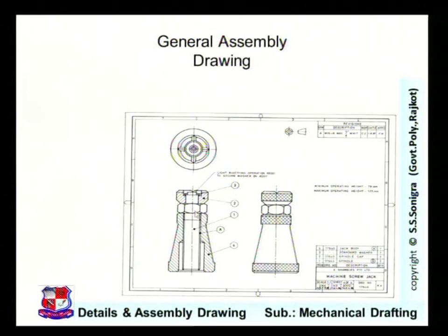And as the top view is drawn over here, the symbol is represented over here. The symbol shows it's the third angle projection method, and a revision table is drawn over here. Say revisions, in component A revision is made, and whatever revision is there, its description is shown over here, with reference number, date of revision, and approved by, represented in the revision table.